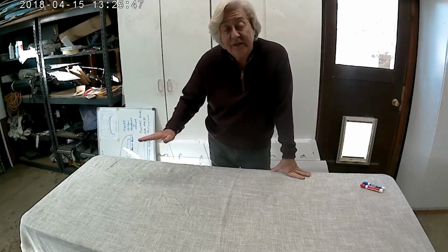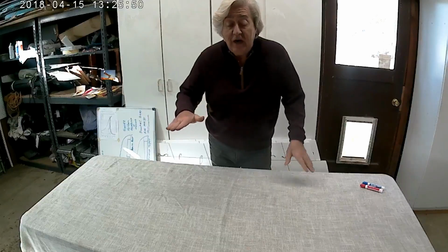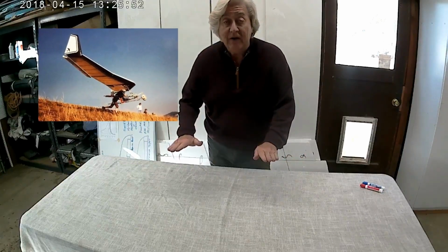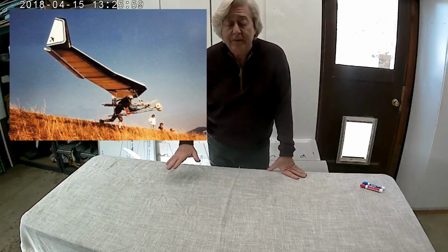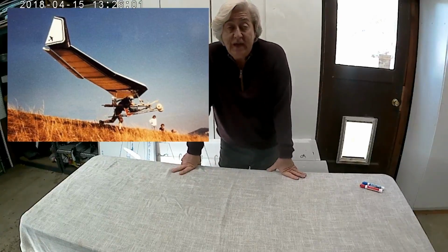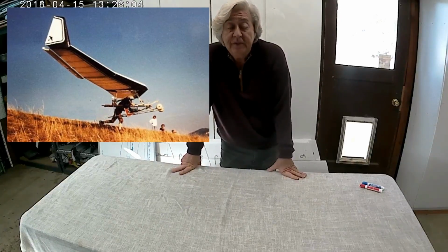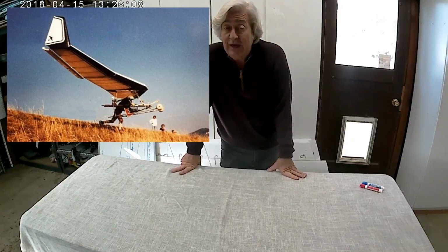The Mitchell wing is an excellent example of don't put control surfaces on your wingtips, or actually don't have the wing itself be a control surface. The Mitchell wing has control surfaces out at the wingtips. However, they are detached and stepped down elevons. In other words, there's a gap between the wing and the elevon is a full flying wing up and down. Now, that can be an excellent solution, makes the glider easier to build. It can be a little bit heavier. It's a lot draggier though.